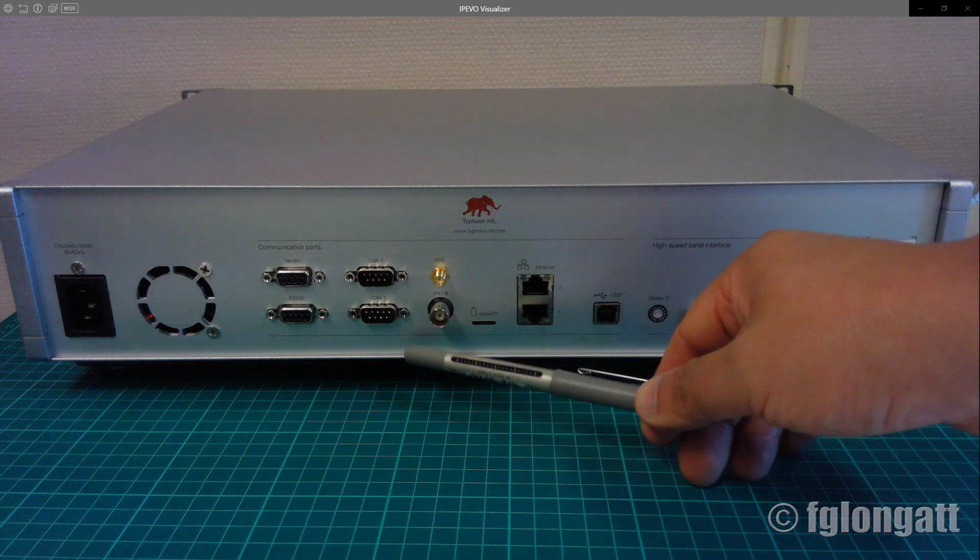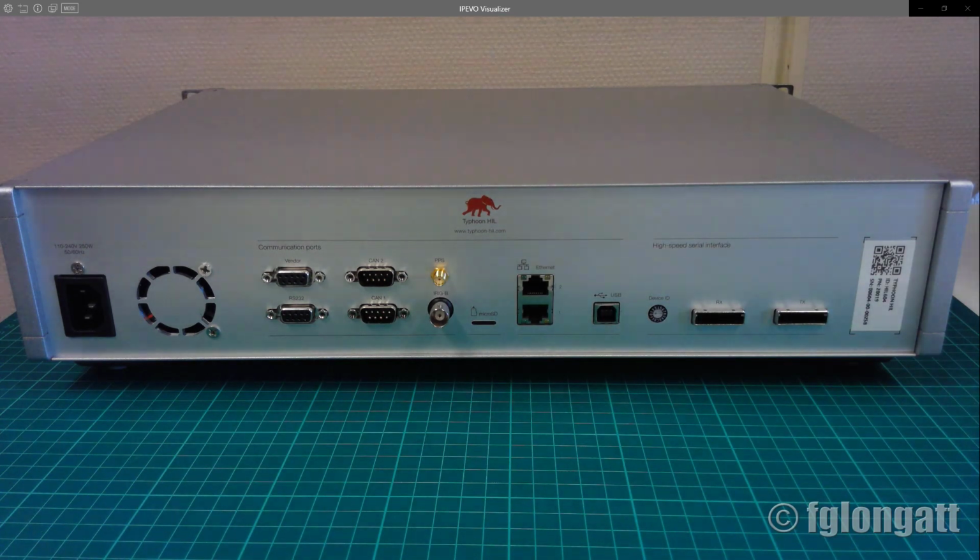And here is one of my favorite parts. If you are working on protection, and especially wide area monitoring, control and protection, you are interested in time-sampled values. If you are using PMUs, you need synchronized measurements, and that comes from using a proper time stamp. In this case, this device has two very interesting connectors over there.